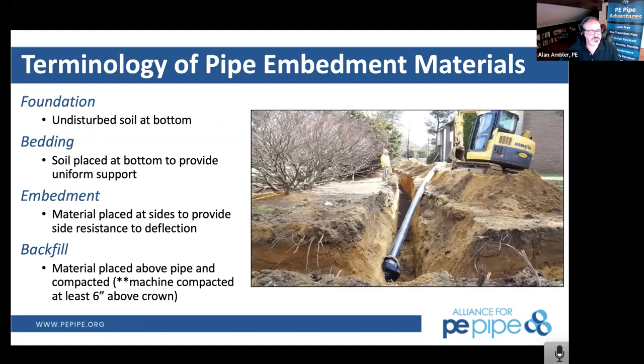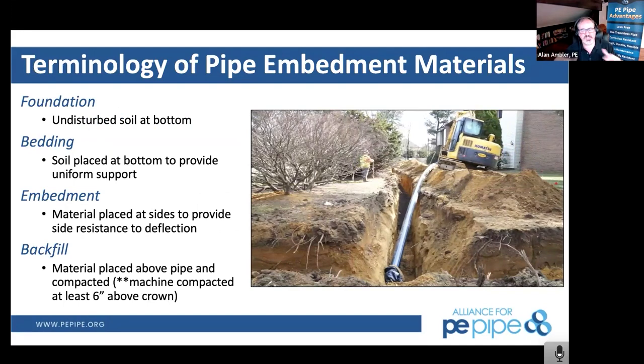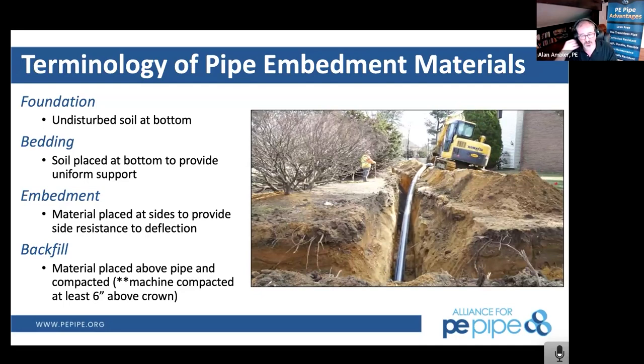This is a video for us, Pete, for one of Richard's places there as well. We saw these two workers being able to put that backfill material on top of the pipe before. Now they're simply putting the pipe into the prepared trench that had bedding, which is set there to be able to receive that pipe. Again, we're not putting anybody in the trench in these scenarios, and they're taking advantage of that long, productive run by installing all this at the same time. Go ahead, advance, Pete.